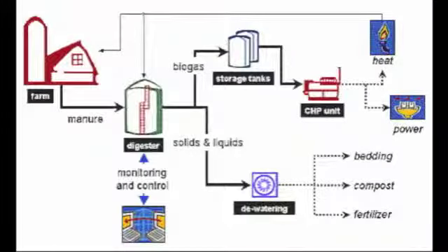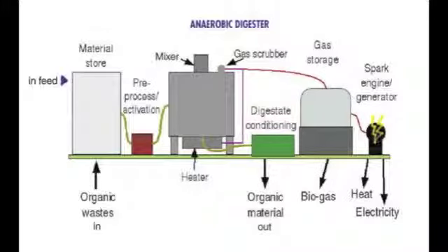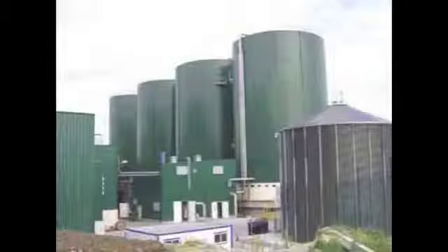Anaerobic digestion is when organic matter is metabolized by anaerobic fermentation or anaerobic respiration in an environment free of oxygen or its precursors. This method has a long startup time and recovery time and requires specific nutrients, trace metals, and constant meticulous operational attention. Anaerobic digestion is more susceptible to changes in environmental conditions and gives off high sulfate wastewater that must be treated.